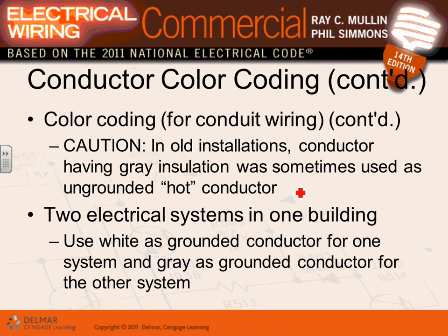In the past, you guys don't care too much, you're not electricians, but in the past, believe it or not, the gray conductor was used as a hot conductor. So if you're doing troubleshooting, I don't know, Adam, if you do any troubleshooting work, if you go work in a building and you find a gray conductor, be very careful, made in the 40s or the 50s, that gray conductor might be hot. Now it's a ground, but in the past it used to be hot.